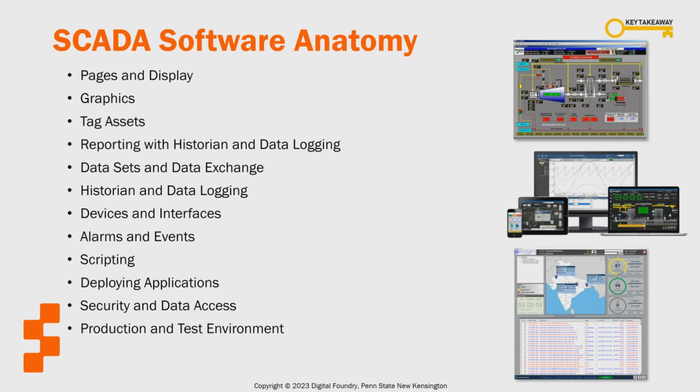For devices and interfaces, the SCADA system will connect to the process through a PLC with a variety of standard open protocols such as OPC-UA or MQTT. Alarms are unexpected and might need corrective action. Events are expected and noteworthy and are reported to determine historical sequencing to the process. SCADA systems may also use scripting, which is an advanced feature that requires high-level programming languages such as Python. These will enhance the capabilities of the system.